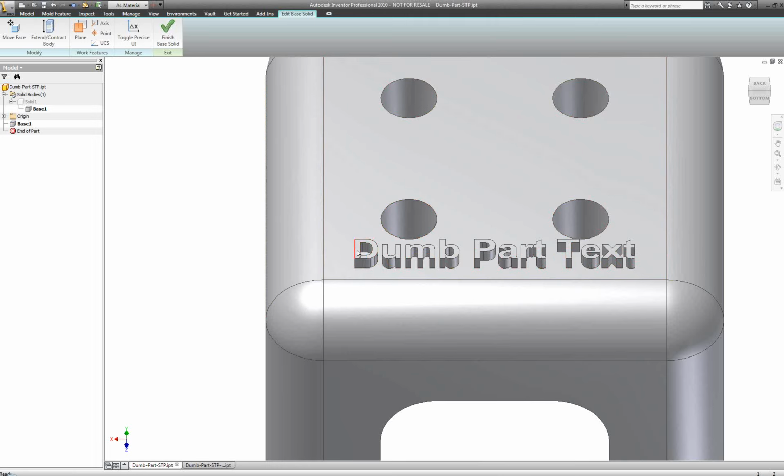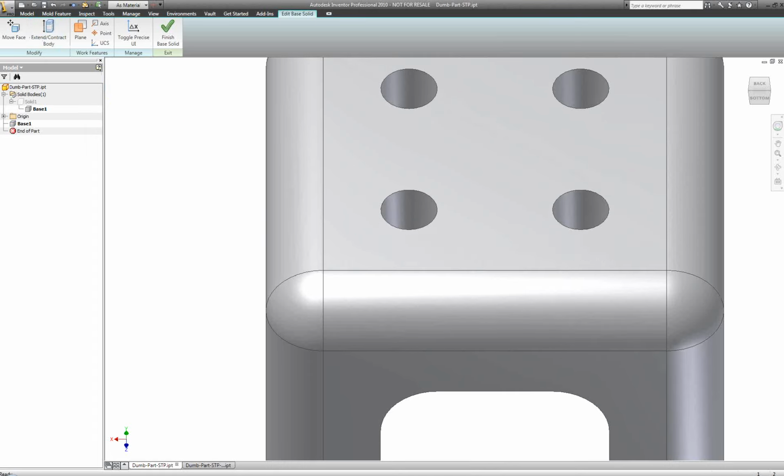So let's take a look at this, and let's expand and contract this information. So if I take, say, this surface here, and I want to now contract this down into the surface of my part, I could simply measure the distance that the text extends off of that surface and move it down in and make it all flush, so that when we go to create this information, we can now contract this down in one big step and make a flat surface.